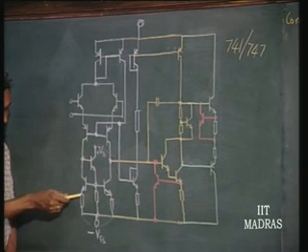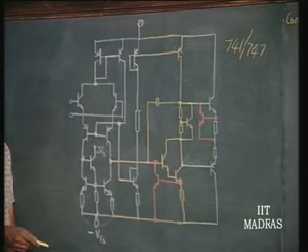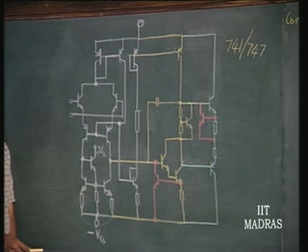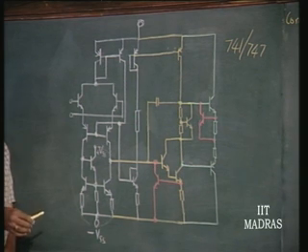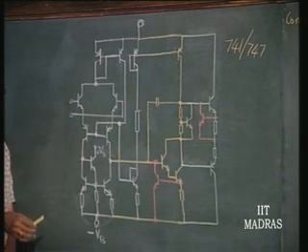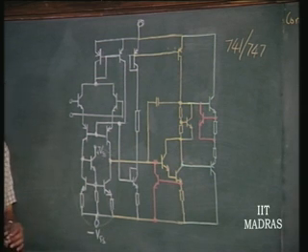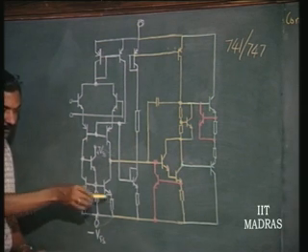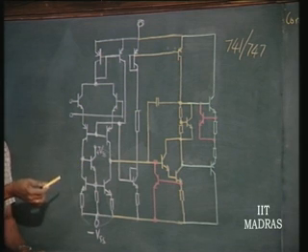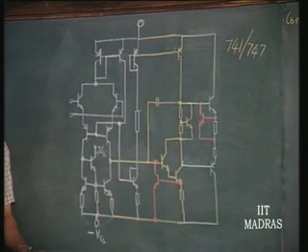Now, in our earlier basic configuration we had not put any of these resistors. Now, note that we have put resistances in the emitters, okay. It is not really serving the purpose of making the currents equal. Currents were more equal before the resistances came into existence, because the resistor ratio is not all that, okay, better matched than the geometries themselves, okay. But we are intentionally putting resistive degeneration. One purpose is automatically served, that is output impedance is increased, but that is a minor purpose for which it is put. The major purpose for which these resistances are put is for offset compensation.